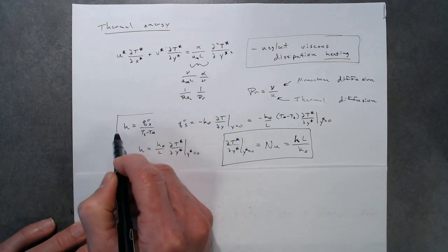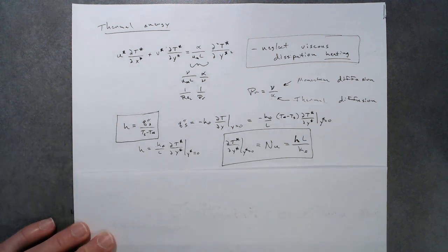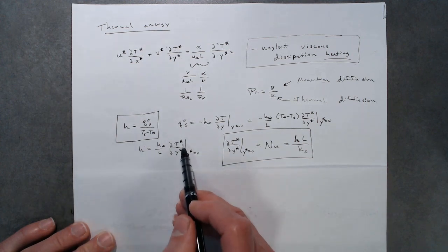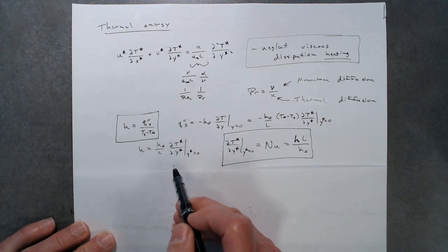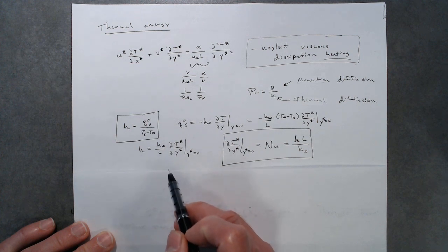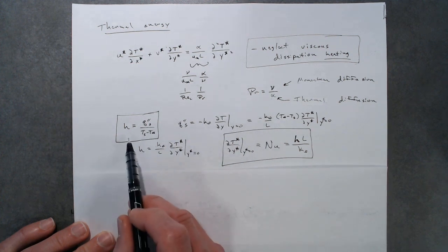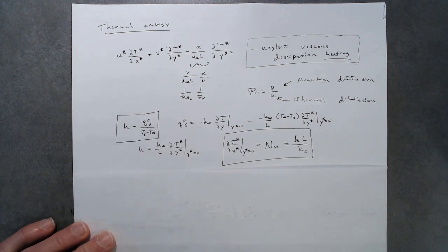So in heat transfer, for convection, we're generally trying to come up with h. And in the problems before, you were usually given h. That's what all the chapters ahead in convection are interested in, determining what h is. Well, if we're able to solve this equation in terms of T star, and we can then find what the derivative of T star with respect to y star is, then we can solve for h from this definition, the fact that h is heat flux divided by Ts minus T infinity, just by the definition of Newton's law of cooling.